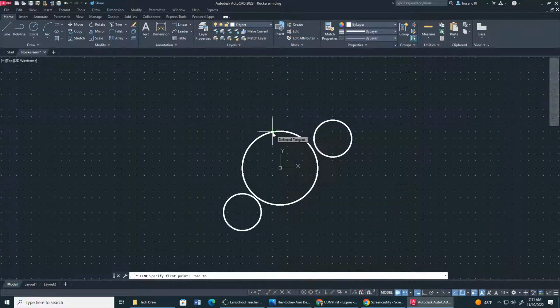Now, a circle is going to come up. When the circle comes up, you're going to see a circle with a line above it, okay? You're going to click that. Now, you have to click tangent snap again. You see how it doesn't cut into the circle, right? Right here. Now, if we didn't do that, it would go into the circle. So we have to select tangent snap again, and look at that. It readjusts for you. I'm going to press escape, and I'm going to do it to this side, okay?